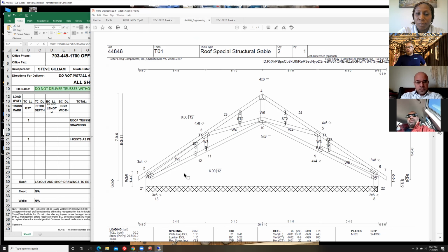And by looking at the CDs, we know that the rear of that plan has big upper transom windows, rectangular, trapezoids, whatever the layout that those have. That means we have to have it as a cathedral gable end in order to get the windows up high. That's one sticking point, or one tricky point, because the standard package is going to be gable end trusses most of the time that the truss company puts in. So we really need to validate where they have cathedral ceilings or cathedral trusses where we need them.